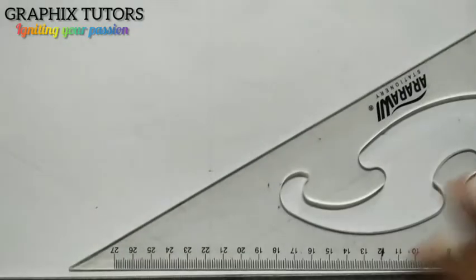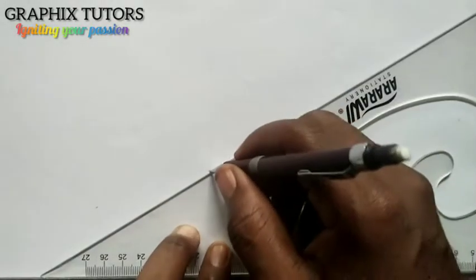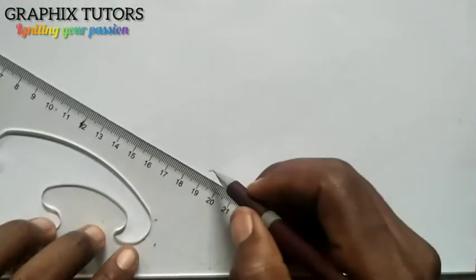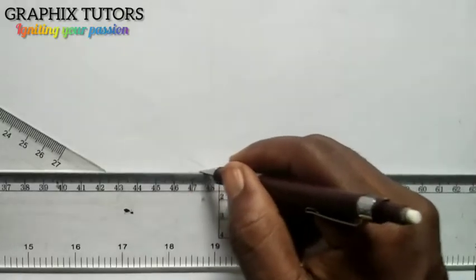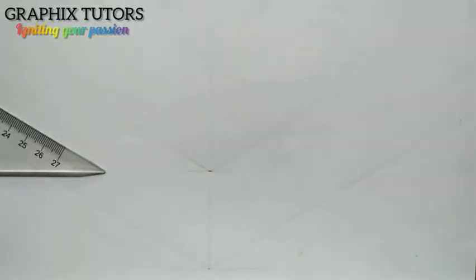So at the same point again, you are going to draw your inclined axis at 30 degrees. So from here, I'm going to draw it at 30 degrees. Like this. This is 30. Can you see that? Now we'll turn it this way around too, and draw this too to be 30 degrees. So that is my 30 degrees there. Now if you place it this way, the angle between here and here is 30, and here and here is 30. I'm using my faint line.